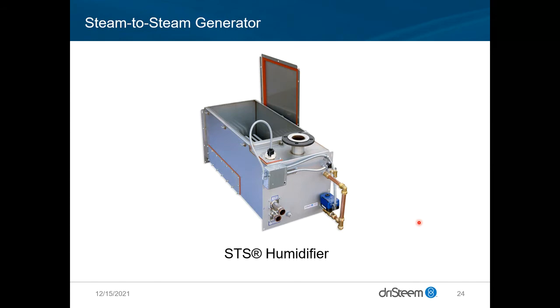Here's a shot of one of those steam exchange units that we looked at before. Again, we're going to use boiler steam to create chemical-free steam to make sure we're not putting any of those boiler chemicals into the airstream. This is an example of an atmospheric pressure one. Again, one that does not put out a pressure. There are unfired steam generators as well, where they take high pressure steam and create pressurized clean steam out.